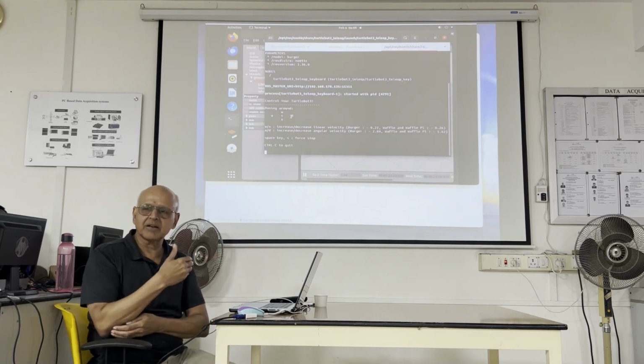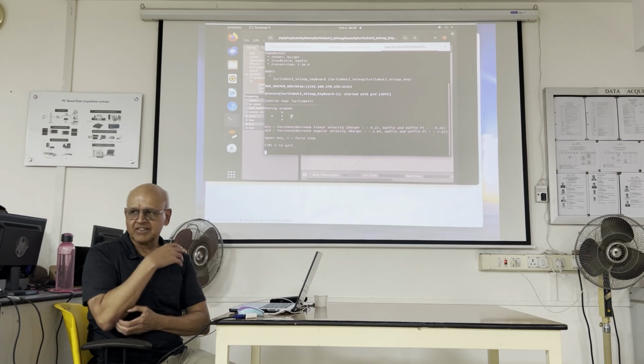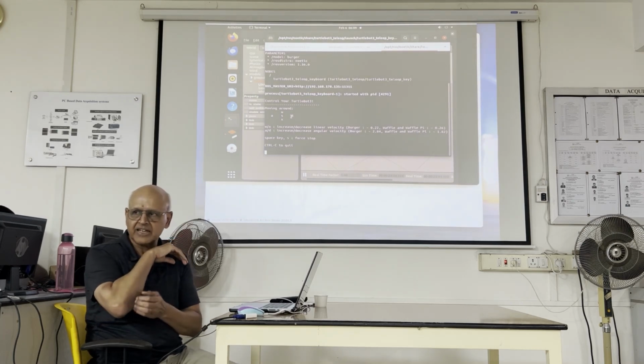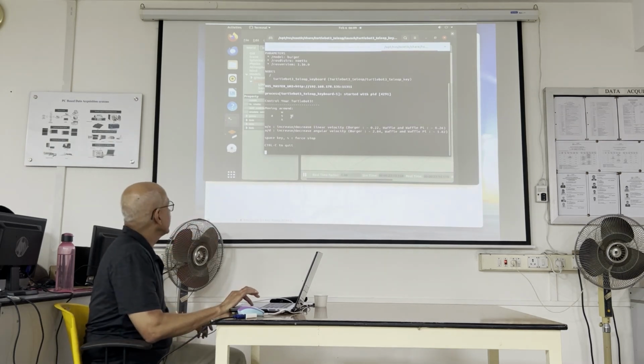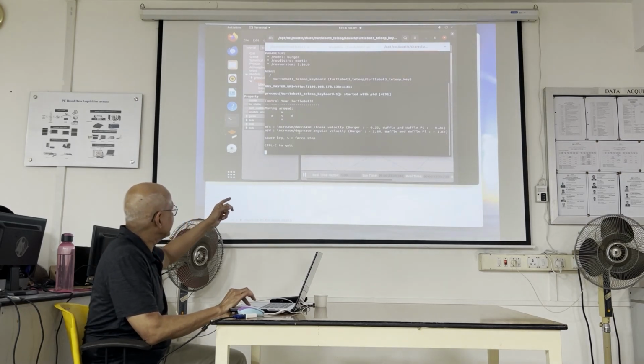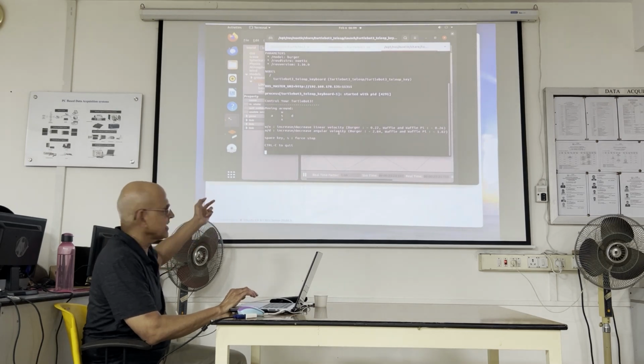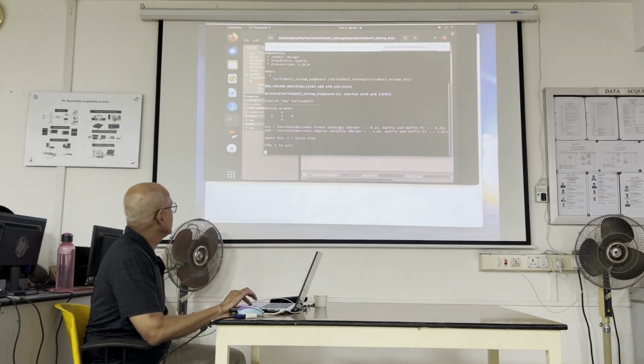They actually made the robots weaker in terms of torque on this. I don't know why, maybe it was a cost factor. So, 0.22. Look at this pattern here. This is how you make it move around. A and D increase and decrease angular velocity. A is increase, D is decrease, right? And W and X increase and decrease linear velocity. And he says for the burger it's 0.22. The rotational rate, the highest value for the burger is 2.84 radians per second.